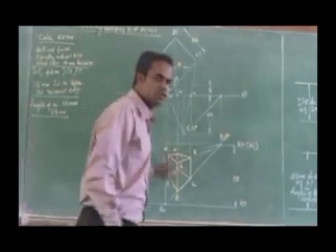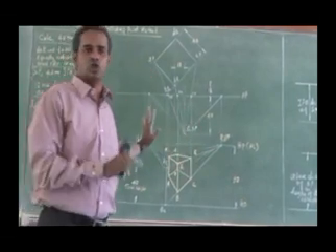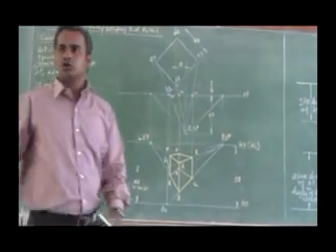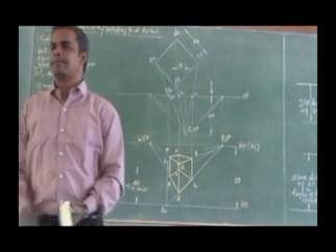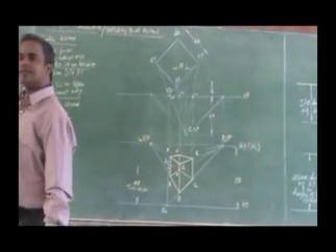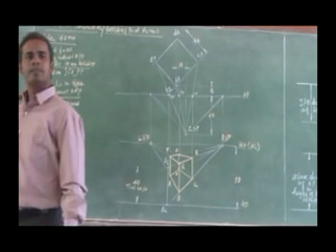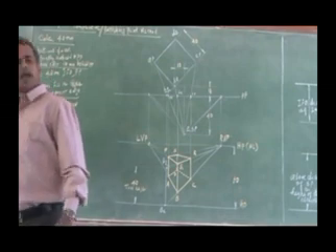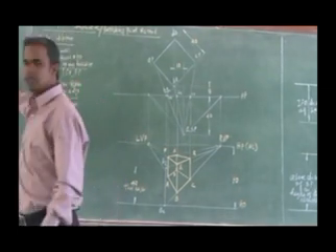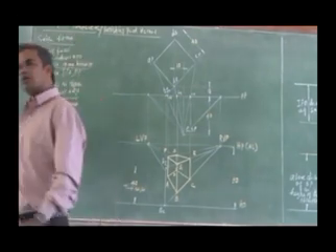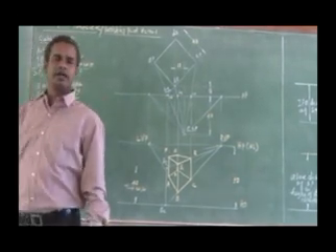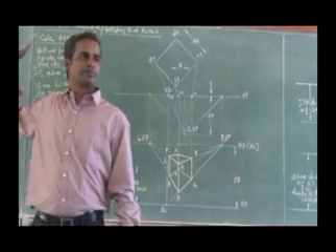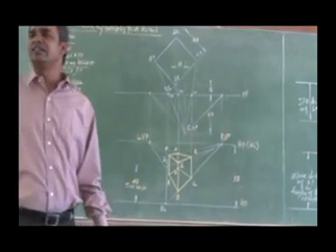Up to this, we have seen square pyramid, square prisms, cube. So problems you may have, suppose instead of the square pyramid in the previous method, if it is a hexagonal prism, you have to draw the top view as a hexagon. Front view will be the edges of the hexagon. Vertical edges you may have 4 edges. That you have to join to the station point as usual in the previous method. So instead of square, you may have a hexagon, pentagon also. Pentagonal prism or hexagonal pyramid. So mostly we will be asking in this. Okay. Is it clear? You have any clarification in there?